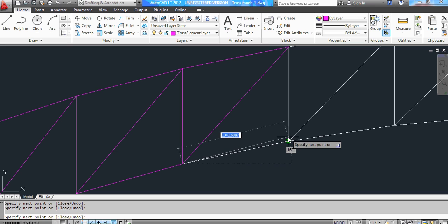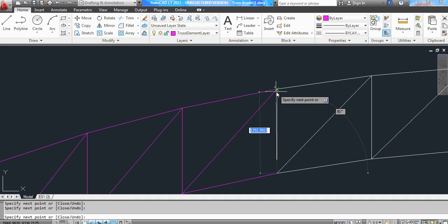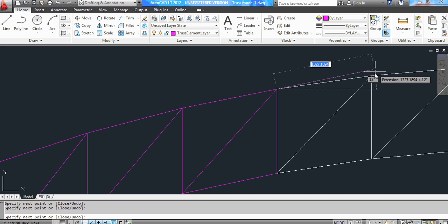Please avoid using polylines, because polylines are not line objects. The software will only read your line objects and not your polylines. It's important you also note this. And if you can ensure continuity as you click on points, that can help, but where you can't ensure that, just let it go.